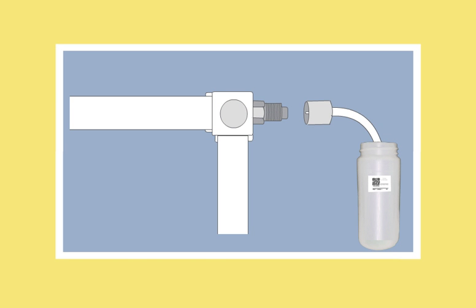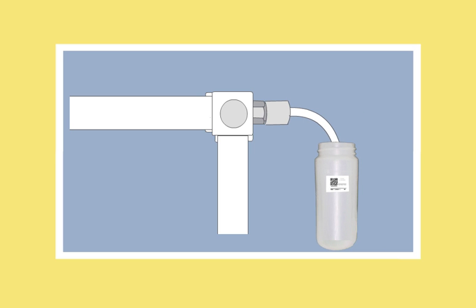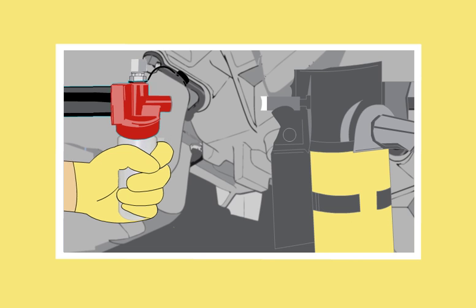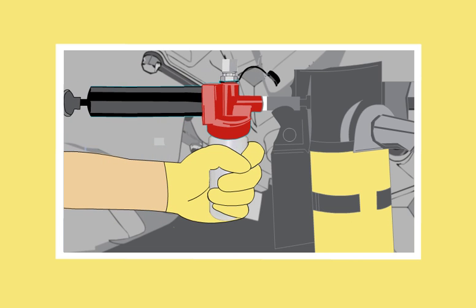Before you begin, you'll need to clean the sample valve prior to use. Insert the needle probe on the end of the pump tool into the valve to flush out the fluid. You do not need to use the pump. Next, attach the sample bottle onto the probe instrument, then securely attach it onto the engine sample valve, inserting the needle probe into the valve.